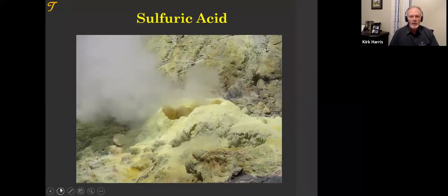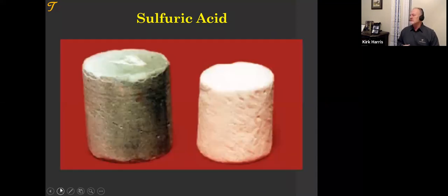Sulfuric acid is another. We did a project on geothermal wells near a volcano in North Sumatra, where we had fumaroles like this of sulfuric acid, bubbling sulfuric acid in the rock, and we lowered hundreds of cylinders of cement and measured over weeks and months the corrosive nature of the cements. We were doing this to test an anti-corrosion cement, a calcium aluminate cement, and that is shown on the left, our Portland cement on the right.